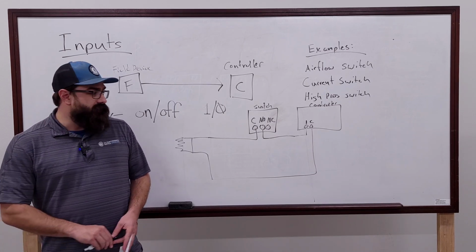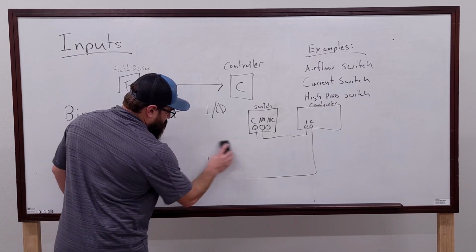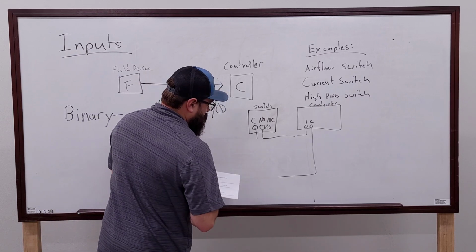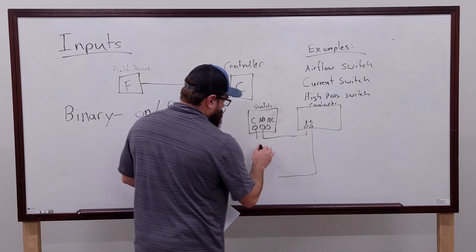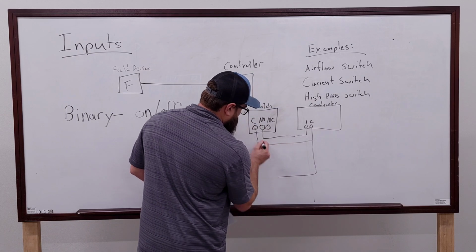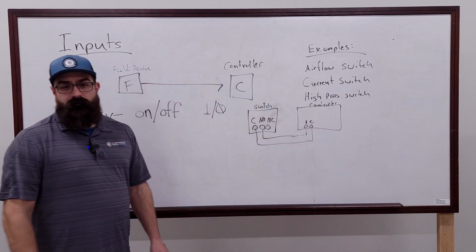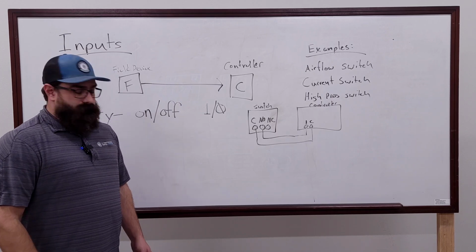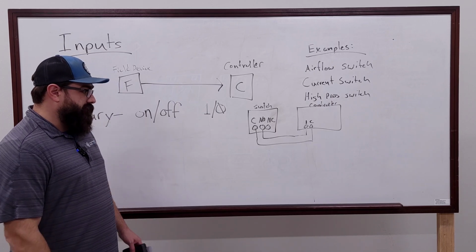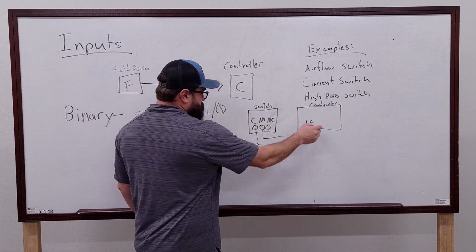So you can just literally take a wire. All this goes away, and then you just have straight to your field device. So you don't need anything in between. You can literally just run a 2 conductor straight from the field device straight to the controller.